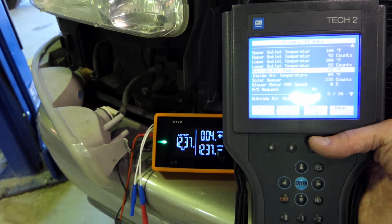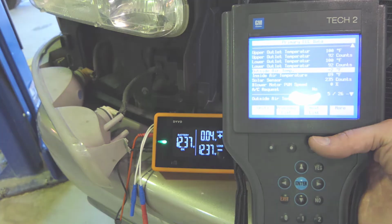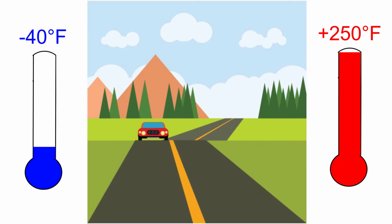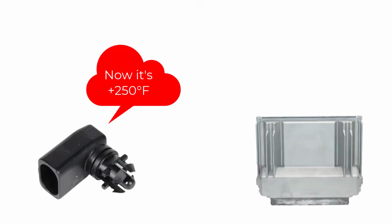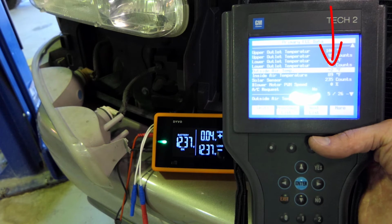However, on this vehicle, the value shown on the scan tool isn't the live reading. It's the last value the control module wants to keep. The manufacturer does this because they know it isn't possible to have a normal environmental condition where the temperature changes from -40 to 250 degrees within a second. So if the temperature sensor reports a big change that quickly, the control module holds on to the last known value and reports that on the scan tool. That's why it still says -2.